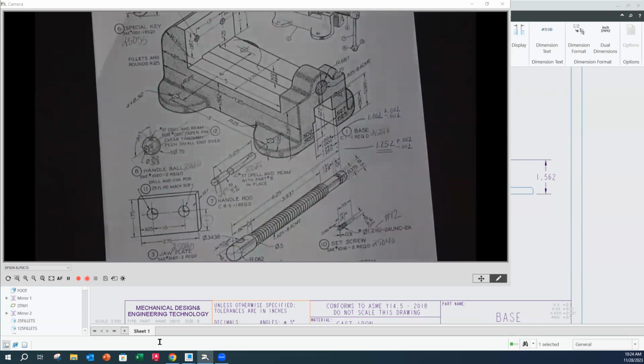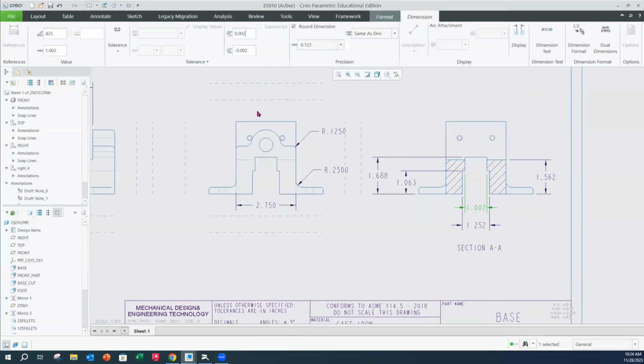And when I say 2, it's 2000ths, 0.002. So now we're going to go back over here to our drawing, and we're going to make sure that our tolerance is up here, okay? And that's +2 on the top and -2 on the bottom, all right? And that's 0.002 and 0.002. Now we're going to switch our tolerance over, and we want it to show as limits and not nominal. So I'm going to go to my limits then, once I have those in place.